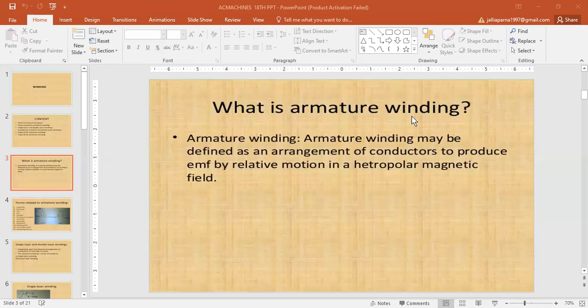If the coil span is less than the pole pitch, then the winding is fractional pitched. In this case, there is a phase difference between the EMFs in the two sides of the coil. Hence, the total EMF around the coil, which is the vector sum of the EMFs in the two coil sides, is less than in the first case.